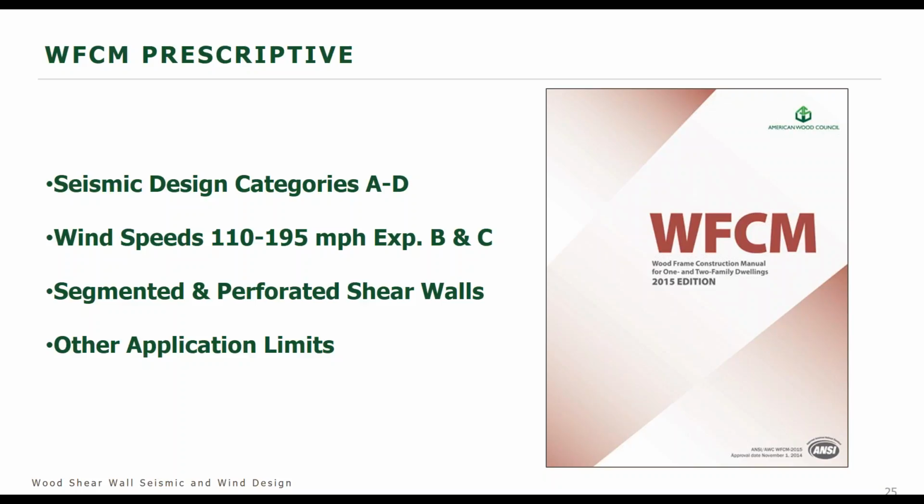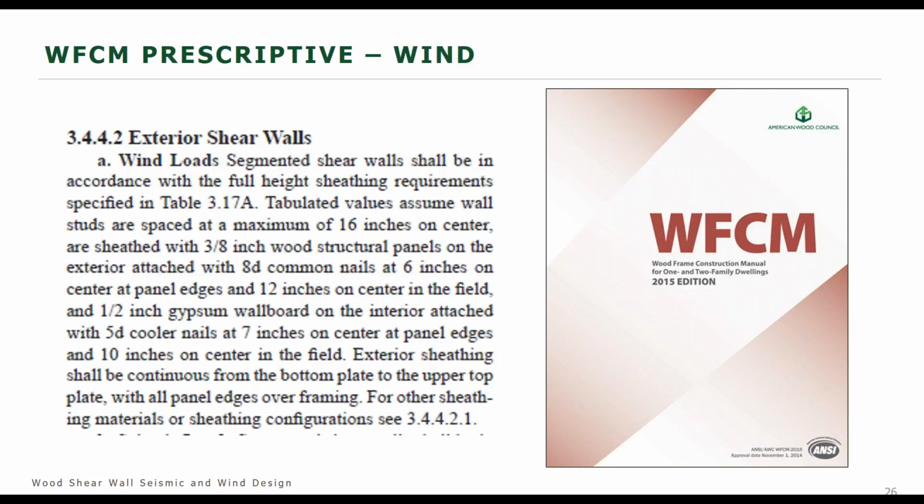Now, I know we mentioned earlier that you can use the WFCM for exposure D. However, for exposure D, you need to use the engineered approach, which we're going to discuss next. If you're using the prescriptive approach, we only have tabulated results for exposures B and C. Again, as I mentioned, we have segmented and perforated shear wall design options in both the prescriptive and the engineered chapters in the WFCM, and those other application limits we talked about related to the gravity loads and the size of the structure.